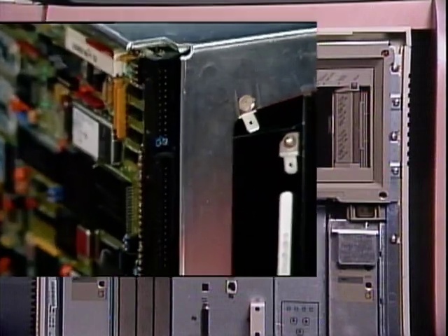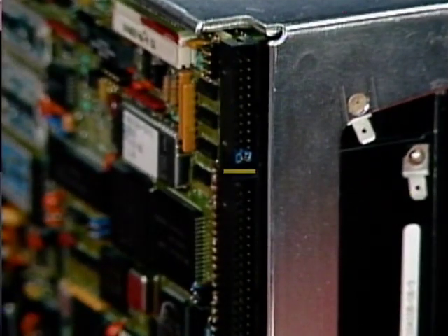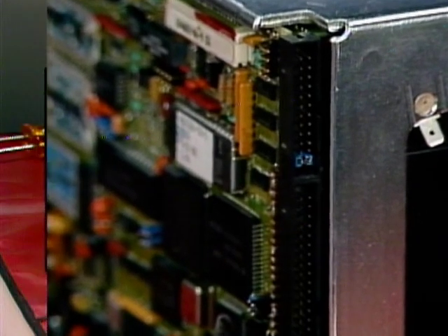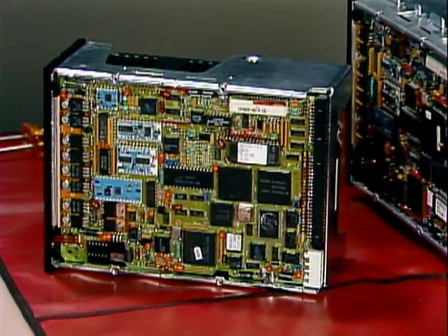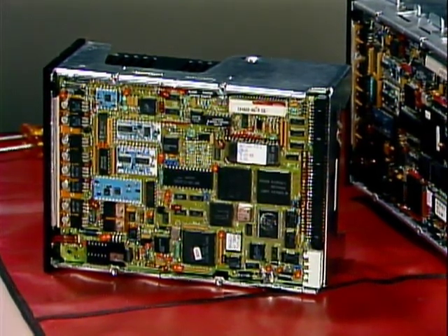On the RZ55, the unit number is selected by jumpers on J2, which is the top connector on the disk drive. The unit number jumper settings are listed in the VAXstation 3520-3540 maintenance guide. The RZ55 device electronics board contains several jumpers. These jumpers are set to the appropriate configuration at the factory and should not be changed.